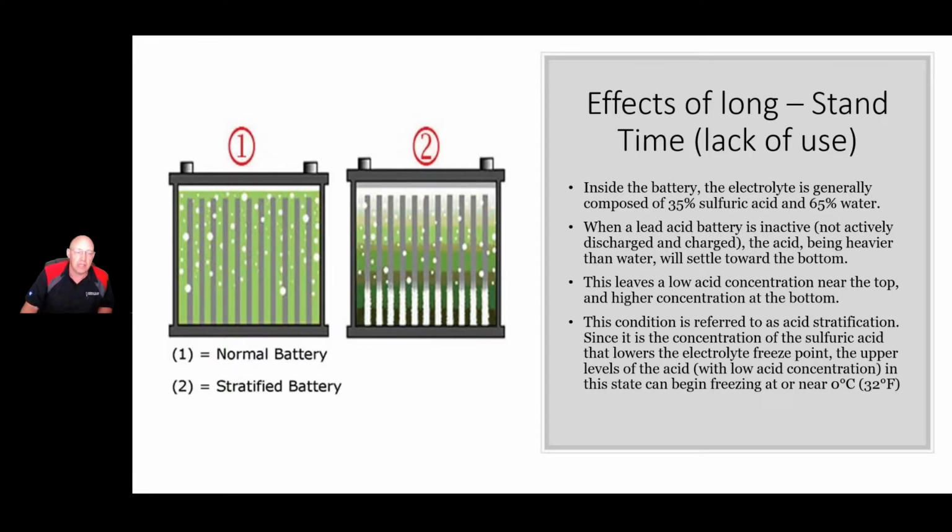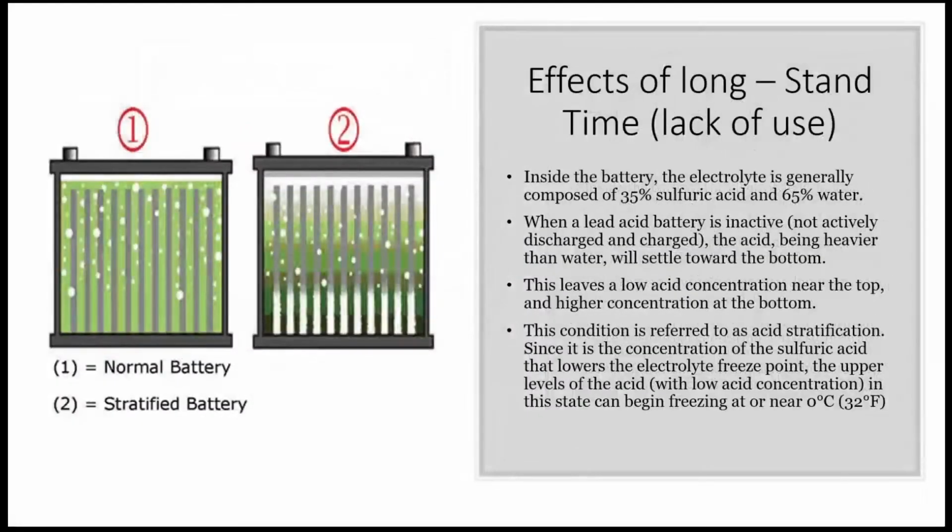So what happens is, as you go back and forth through all of these temperature fluctuations, the battery tends to get the acid level down inside of it, and the acid starts to settle down around the plates and starts to short the cells in the battery. I start to get the mineral concentration in one place at the bottom of the battery, and rather than being suspended as in a normal battery, all the minerals start to compress and come into this area. The battery then starts to get shorted cells because all the minerals are sinking to the bottom, shorting the cells of the battery.